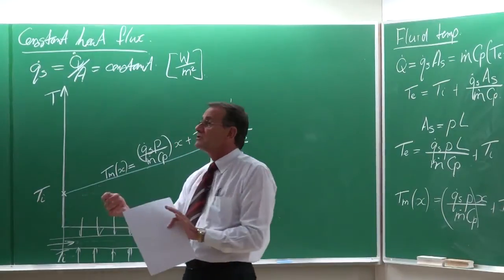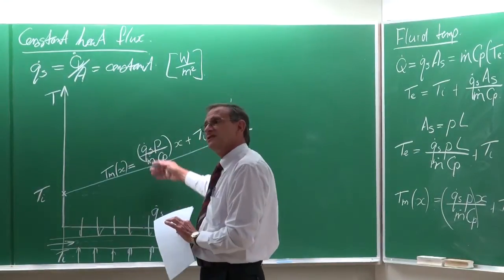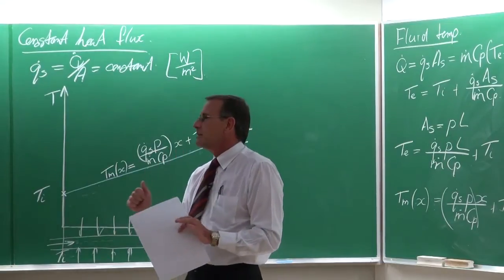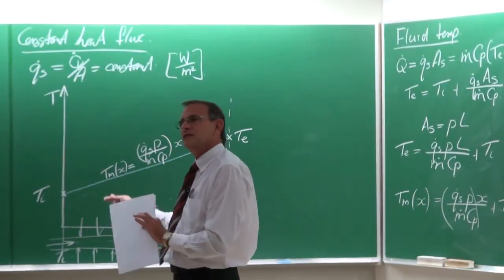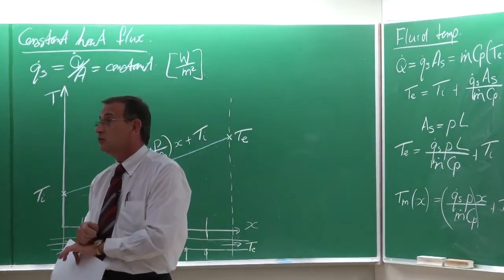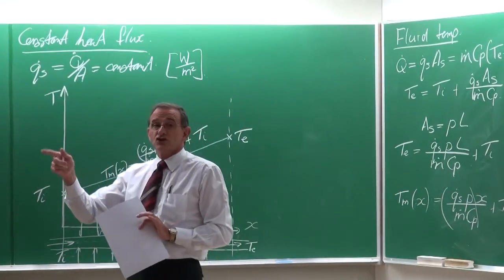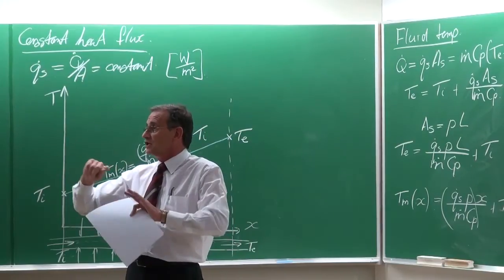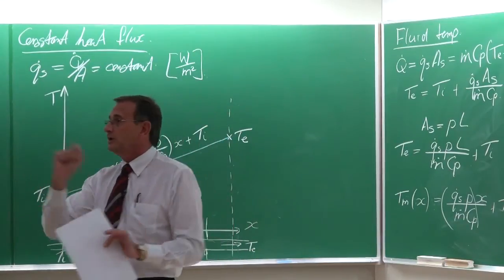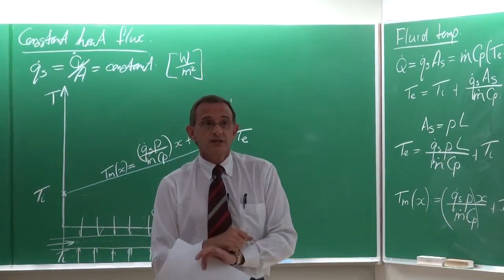Okay. Now, normally you will see in heat exchangers, or in most heat exchangers, the temperature differences are quite moderate. Okay. A good rule of thumb for design is about 10 degrees Celsius. And over 10 degrees Celsius, you'll see that the Cp value almost doesn't change, typically for water and for most other fluids and gases. That would be the same for the density. The viscosity might be something different, changes more, but again, it's going to depend on the application. Okay. Right. Any other questions, ladies and gentlemen?